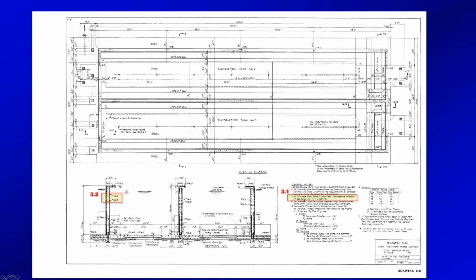And then what is the bar size and spacing of the outside walls? Well, that should be pretty easy too. You just come over here and horizontally, they're number 6s at 12 inches, and vertically, they're number 7s at 12 inches. Now, you said something else about spacing. Do you have any idea what that spacing question was? I can't remember right now offhand.